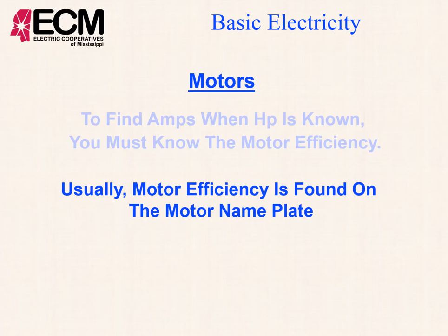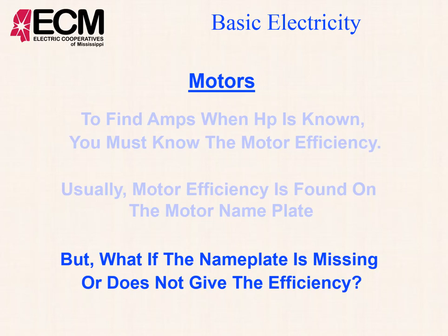There was a point in time a few years back that the efficiency of all motors had to be increased. It was a government regulation. They were in the 80%, high 80%, and they had to get them into the 90s. The way they did that was with less friction, better bearings in motors, brushes, stuff like that, and also with better insulation in the wire so that we didn't lose that EMF, electromotive force.